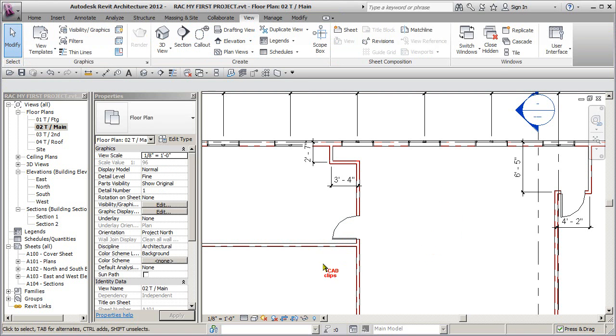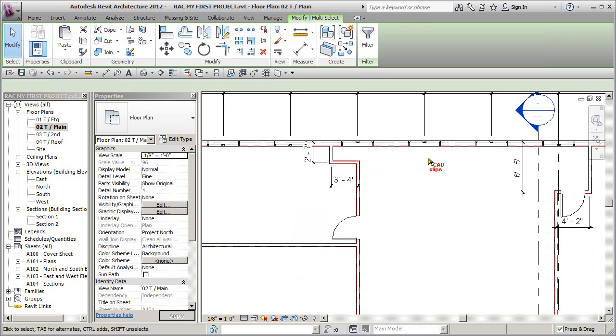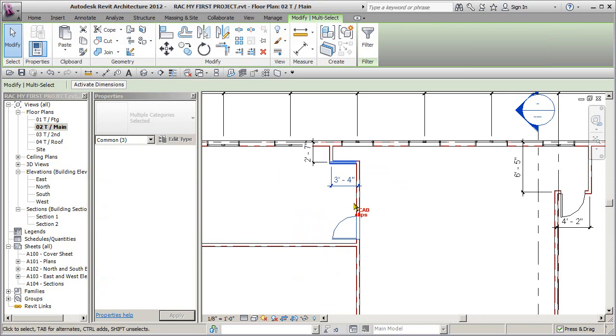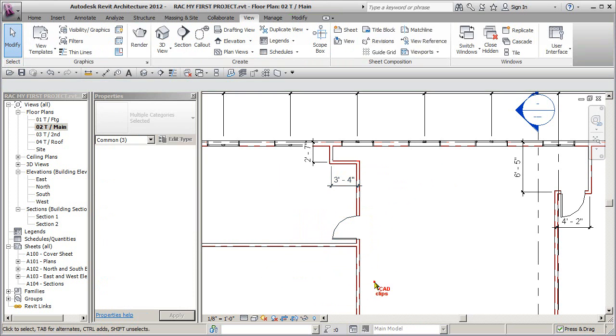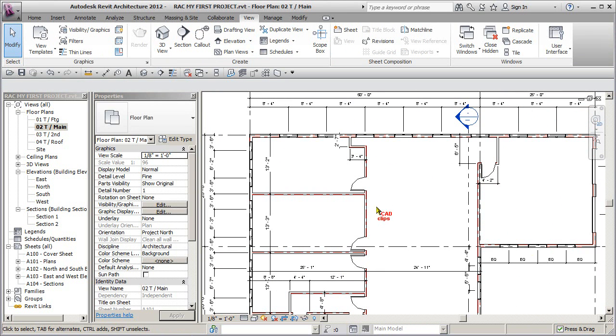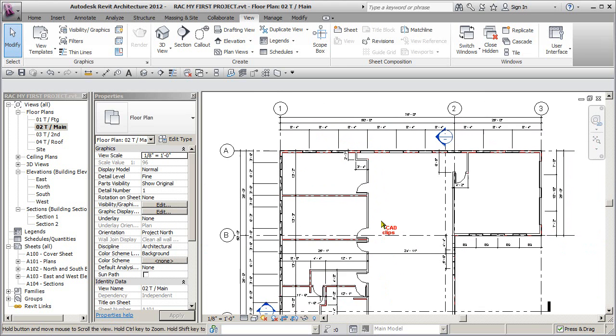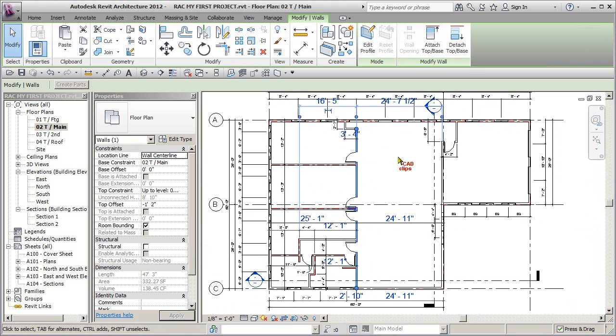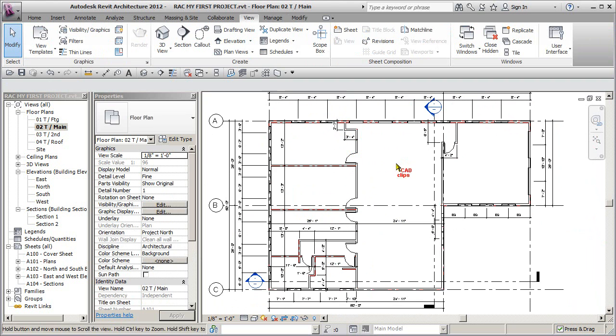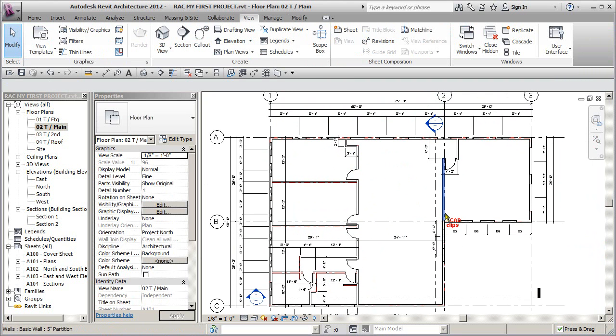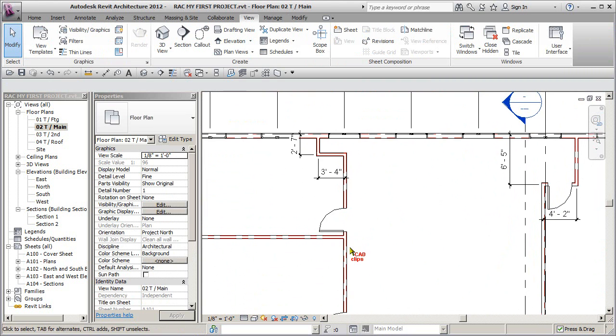Now if we do a window box, we go from right to left. If you go left to right, it's a crossing box. Window box only gathers objects that are 100% within the box. This wall extends all the way down. When you have a wall that's continuous like this, don't stop and start it at each junction. Make that one big wall. Notice how that's one big wall. This stops and starts because the wall changes.